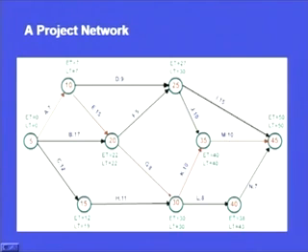Now let us sum up how much time is required. Are they giving the longest path? You see activity A 7 plus 15 is 22, plus 8 is 30, plus 10 is 40, plus 10 is 50. This red line indicates that this is the critical path. So activities A, E, G, K and M represent the critical activities, and the summation of the times of these individual activities is going to give us the longest path.